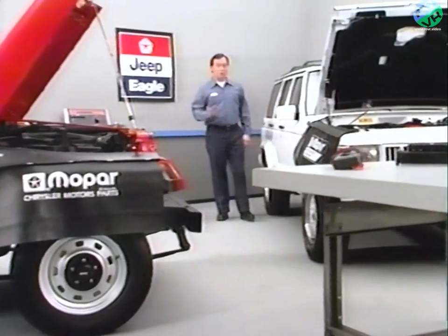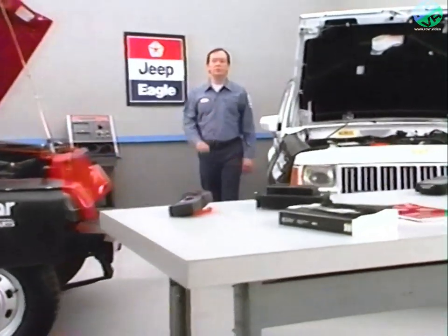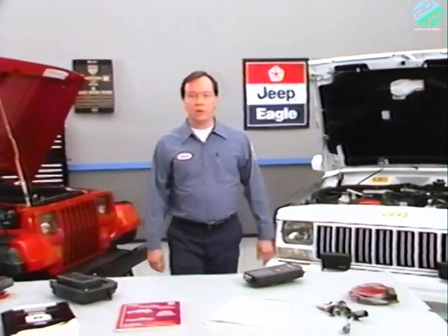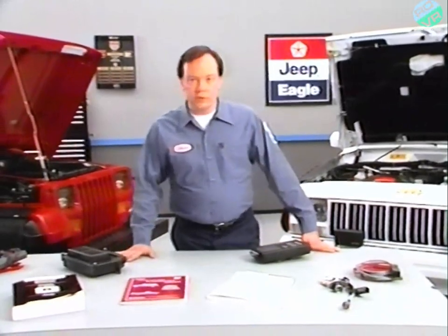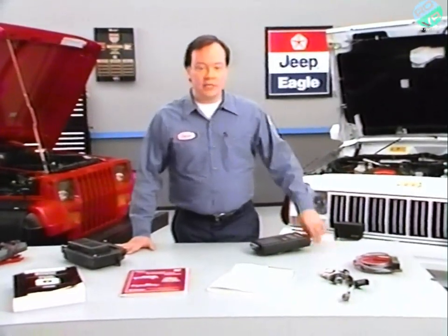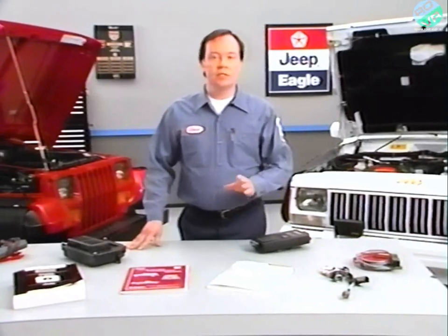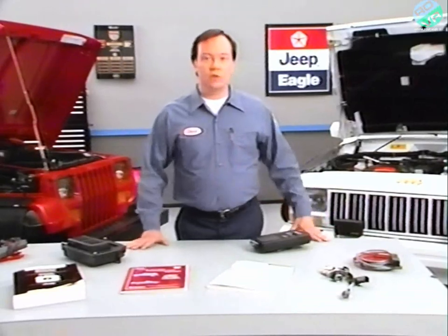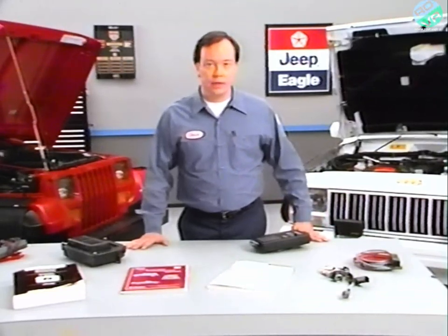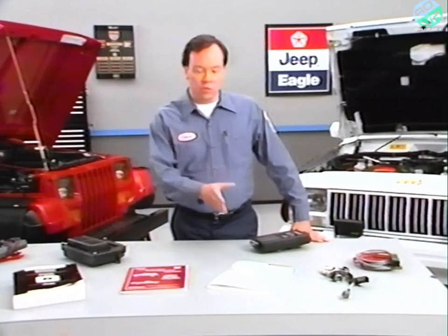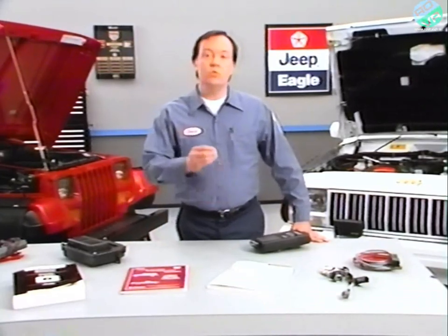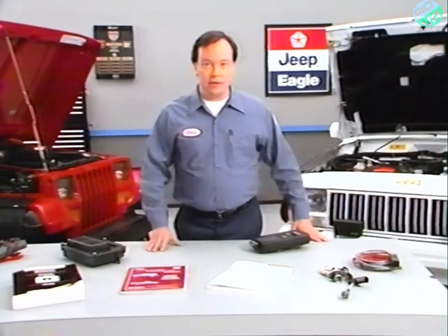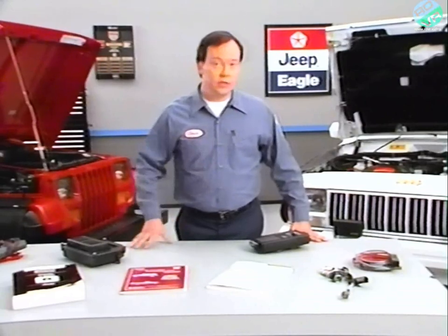If there are no fault messages, you should check all technical service bulletins and hotline newsletters that relate to this drivability problem. If there isn't a pertinent TSB or newsletter, Test DR1 directs you to perform Test DR26A, the first in a series of no-fault drivability diagnostic tests. After performing the tests in the no-fault drivability section, you will have determined that all of the engine control systems are operating as designed and are not the cause of the drivability problem.